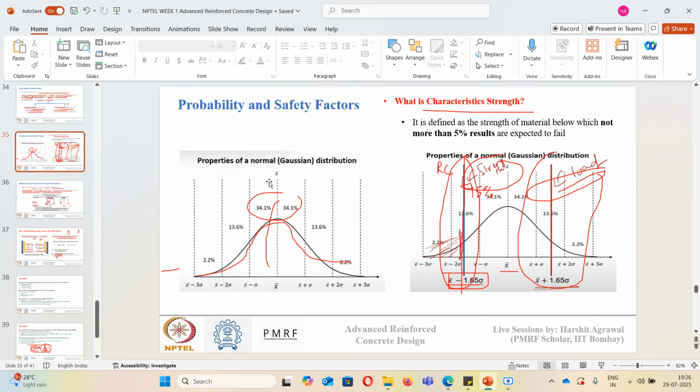Most of the strengths will be around 25 MPa, but some will deviate from 25 MPa because of material variability in the different batches you have poured. This is just a simple representation of the variability that can come. Don't get confused with the values; it is just a representation of the distribution of values. Was I able to clear it a little bit?